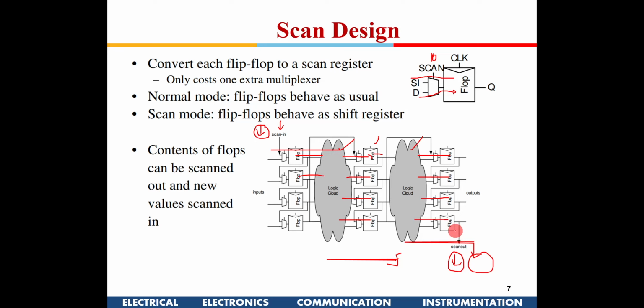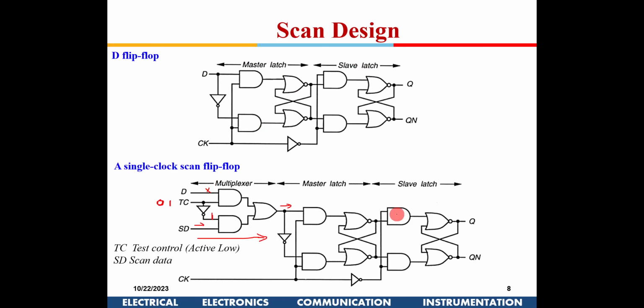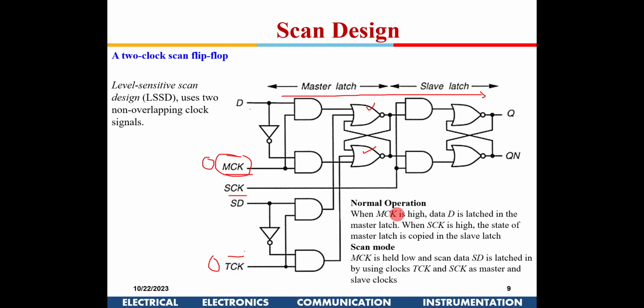Compared to when we did the sequential testing, where we assumed that the flip-flops are working fine, this testing is much more reliable, because even the functioning of the flip-flops is being ascertained here. If you remember from our testing lectures of sequential circuits, we made an assumption there that the flip-flops are working fine. That's not the case here. We can even run a test to ascertain whether the flip-flops are working fine or not.